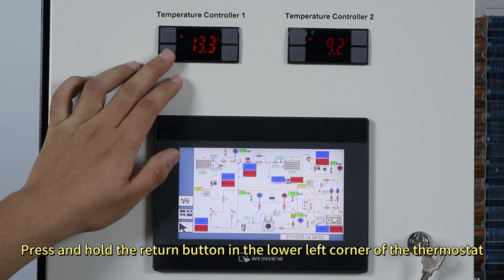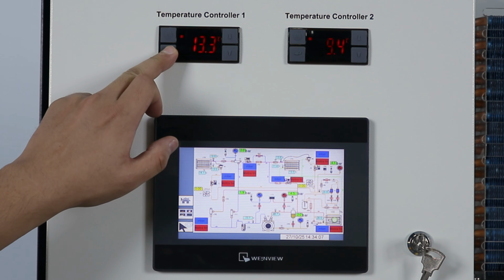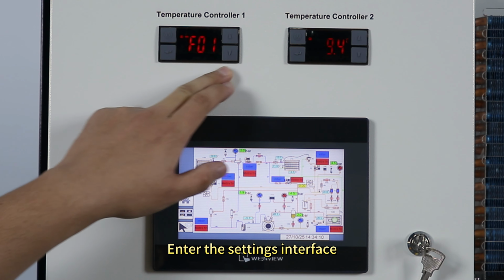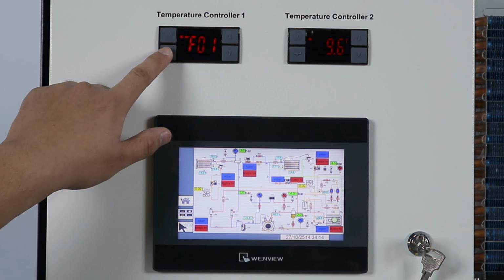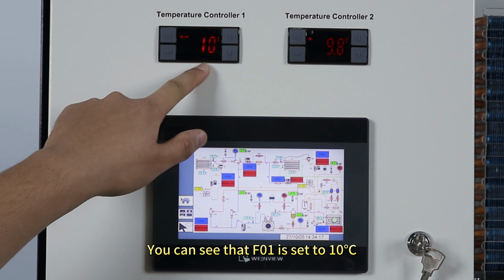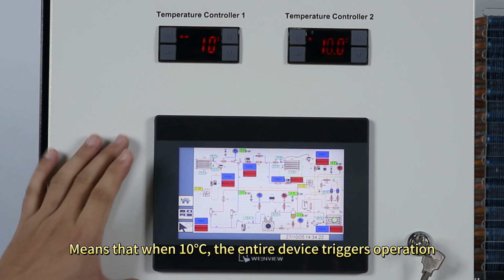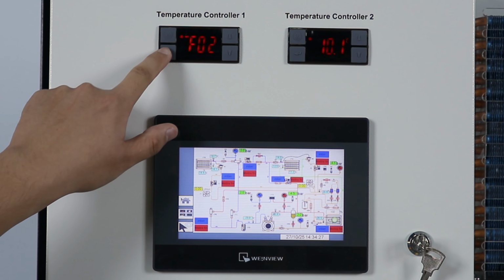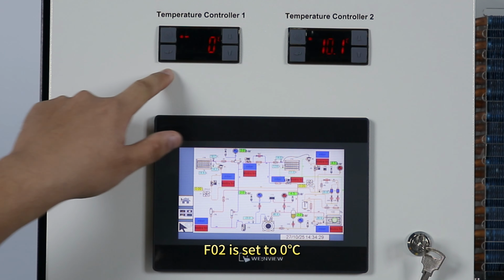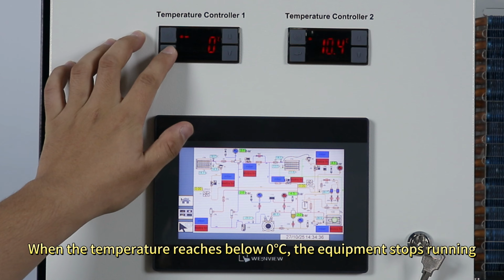Press and hold the return button in the lower left corner of the thermostat. Enter the settings interface. Click Enter. You can see that F01 is set to 10 degrees centigrade, which means that at 10 degrees centigrade, the entire device triggers operation. F02 is set to 0 degrees centigrade. When the temperature reaches below 0 degrees centigrade, the equipment stops running.